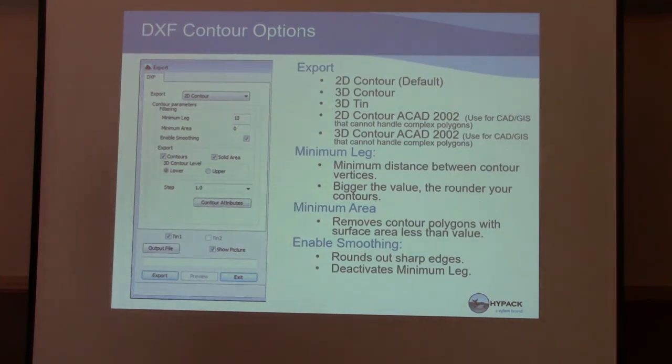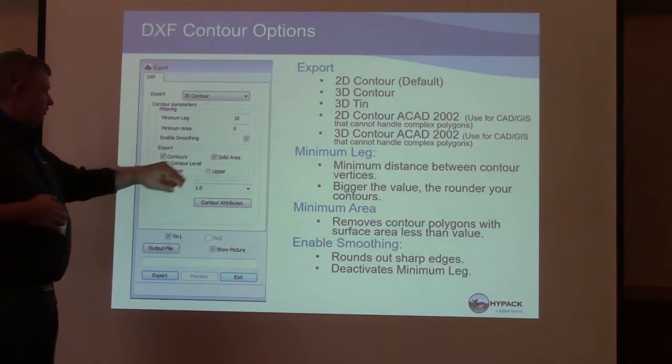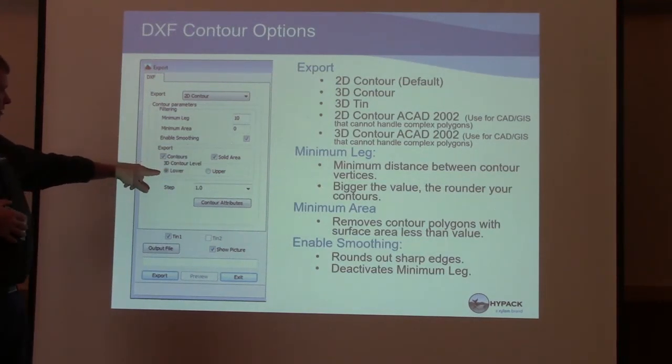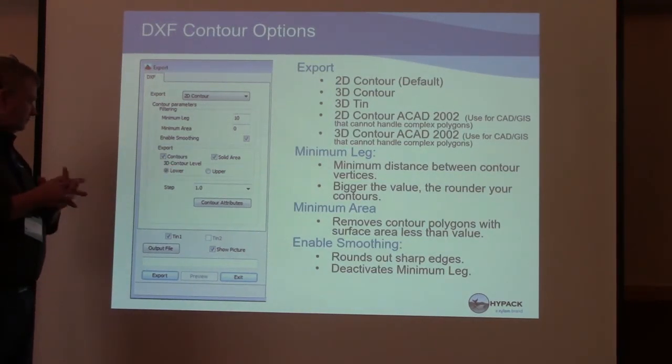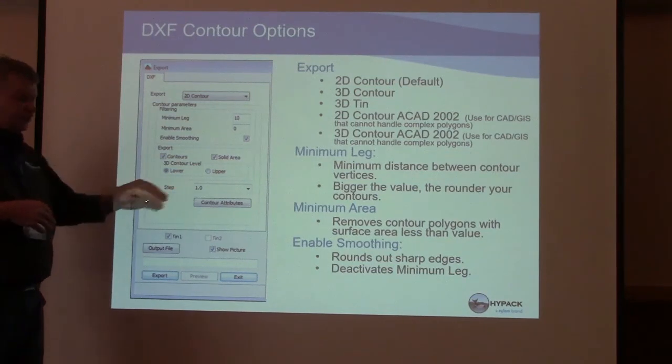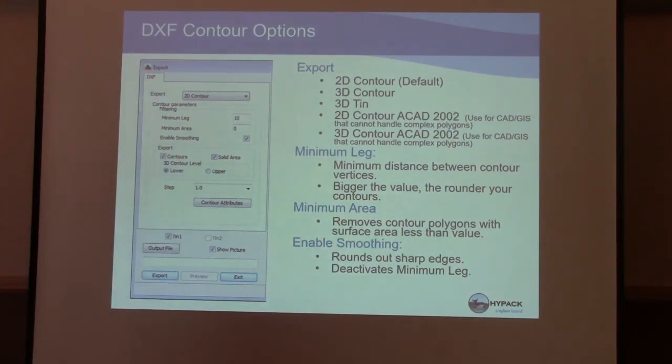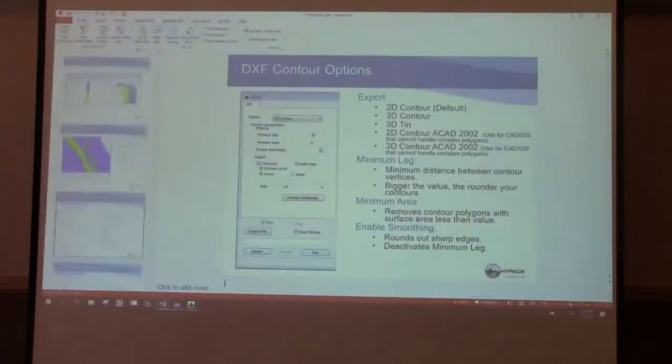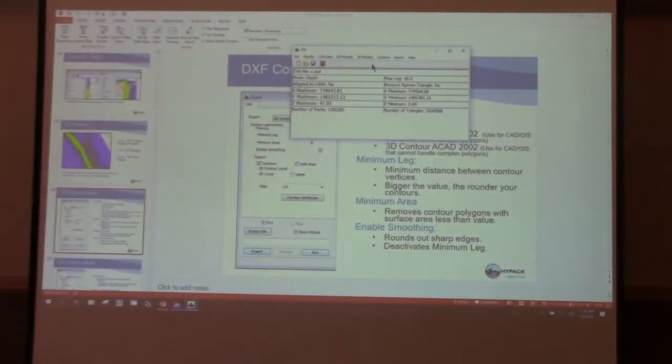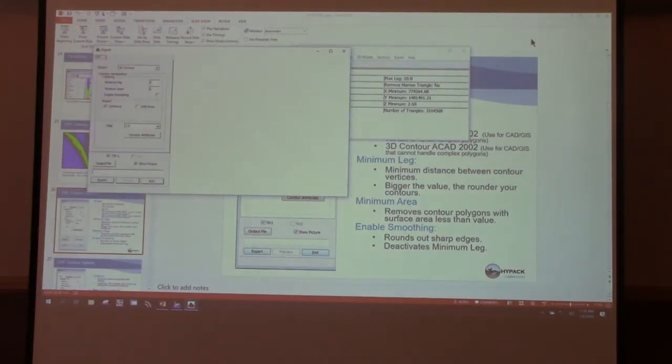You can export contours, you can export solid fill area, and then for 3D contours, lower or upper level. Your step. A lot of times when we export contours, there's a way you do your steps. So, when we go in here, export, DXF.